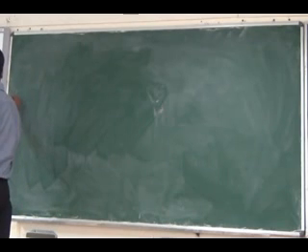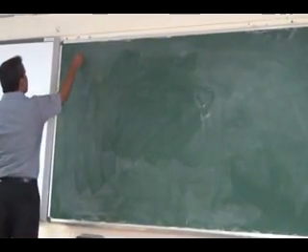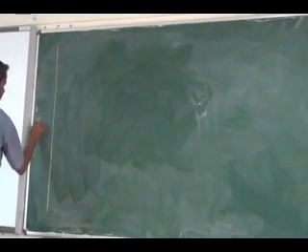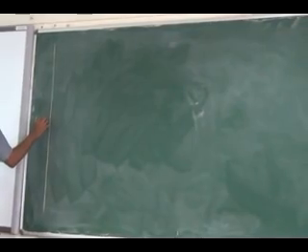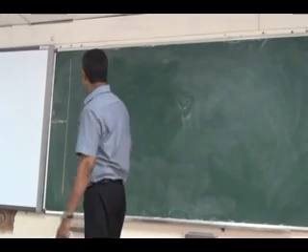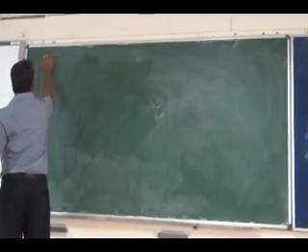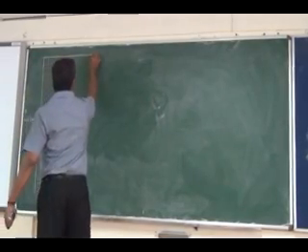In your drawing sheet, you leave a 20 mm gap from the left side and draw the line. Remember that this gap is 20 mm in your A3 drawing sheet. Then all other three sides you have to leave a 10 mm gap.